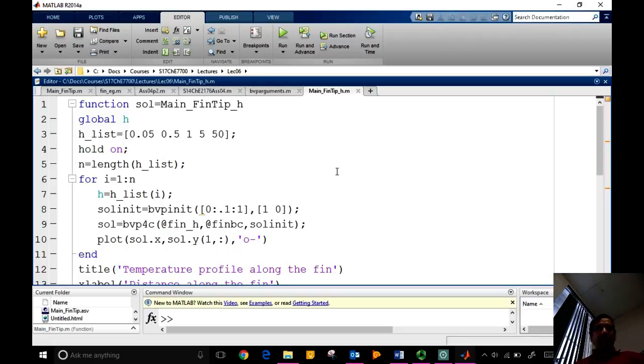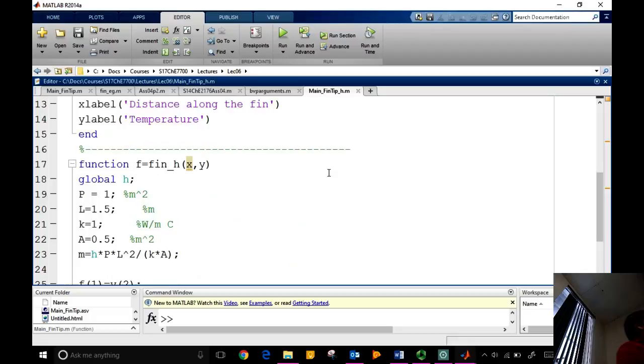Previously I had H equal to this here. But this function is going to be called by the solver many times, so I cannot really change the value of H inside this. So I set it up outside and change it systematically through this global mechanism. I say this variable is global, so wherever this symbol appears, pick up the value.